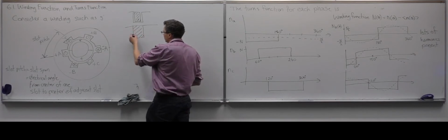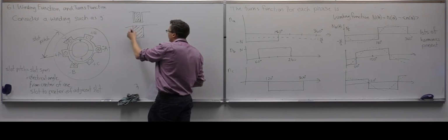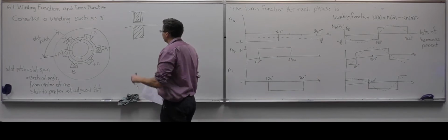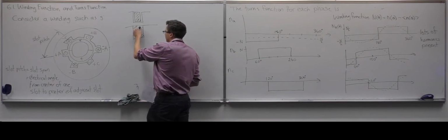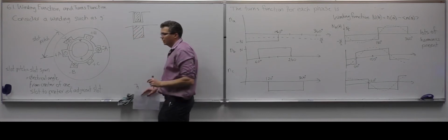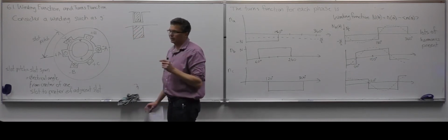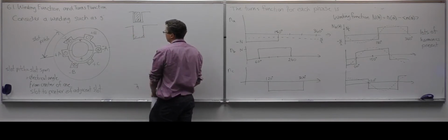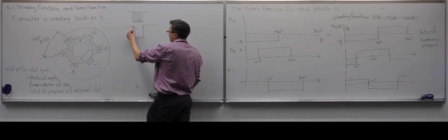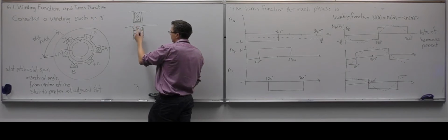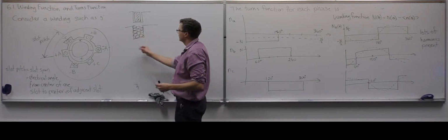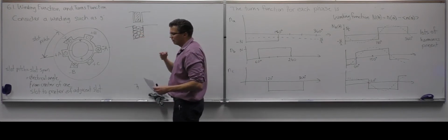But just an aside, in finite element analysis, usually what you do is you define this whole area as being a current, and then you select a current density for this region. You also have to think about the fill factor, because in reality the wires are not nice and perfect like that. If circular, there are spaces between the conductors, so it's not all conductive material. There's lots of air space, and the wires also have some coating on them.